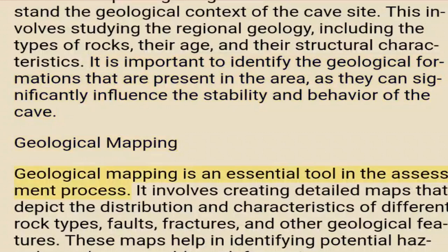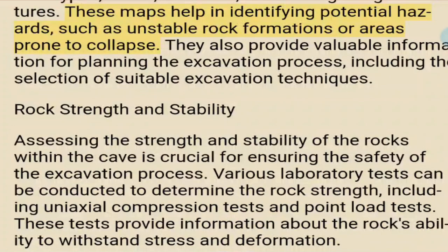Geological mapping. Geological mapping is an essential tool in the assessment process. It involves creating detailed maps that depict the distribution and characteristics of different rock types, faults, fractures, and other geological features. These maps help in identifying potential hazards, such as unstable rock formations or areas prone to collapse. They also provide valuable information for planning the excavation process, including the selection of suitable excavation techniques.